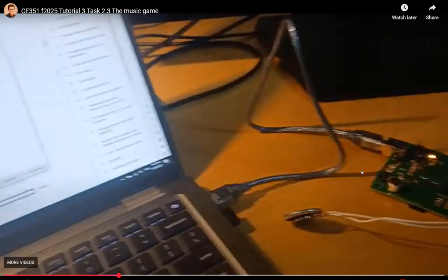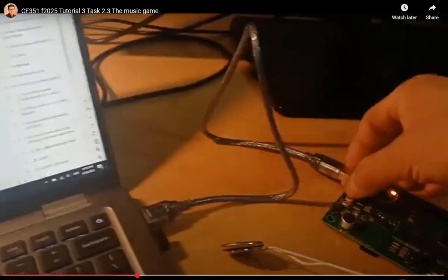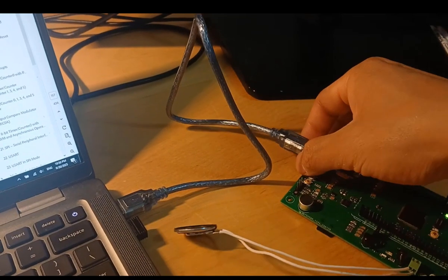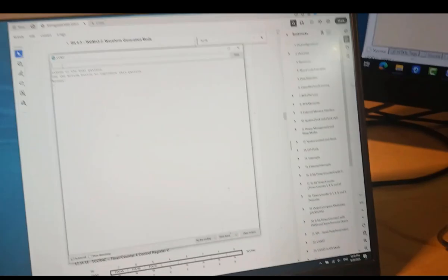So you have to create a little error tolerance in your code: if the duration of the pushing is within this plus or minus error, like several hundred milliseconds, then I play a success song, which means it's successful. Otherwise, play a failing song, which means it fails. So I just played it, right? Just 3 notes, dun dun dun. Then I'm going to press the button 3 times with a very similar duration, trying to duplicate it by pressing the bottom button. That's a success song. And then come back here, press R again.